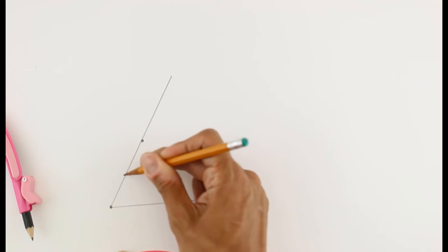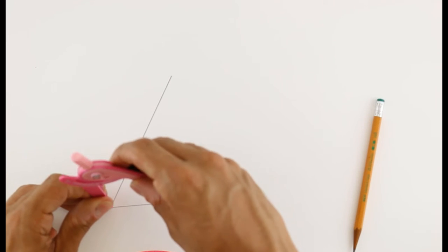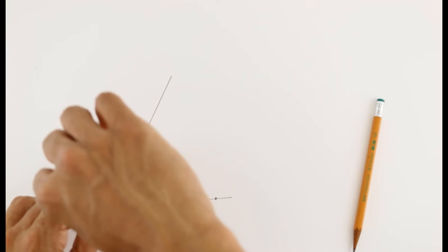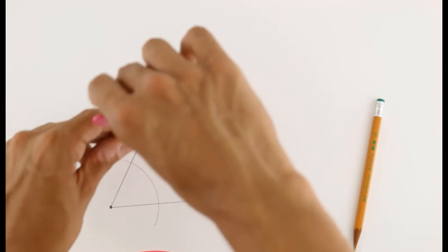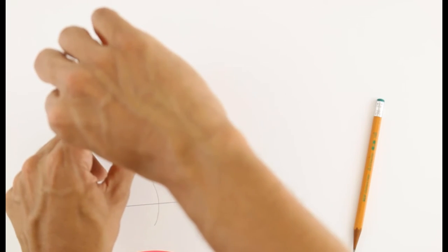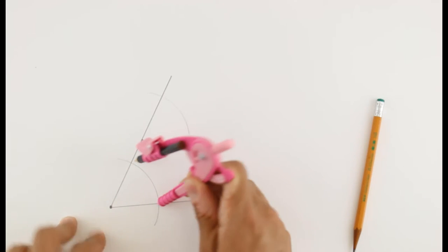Now we know that this is an angle that's created, and that angle size is going to be very important in a second. With your compass at the one point, go ahead and create an arc through the angle that you created, and without changing the distance, make another arc up top from that third point that we established. So as you can see here, I have 2 arcs.